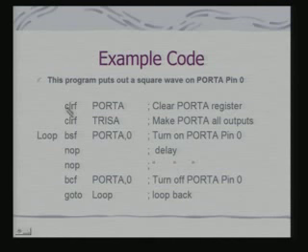Now, you can see here again a usage of the clear instruction for doing hardware programming. We are clearing off the TRIS A register to make each bit of port A an output port.